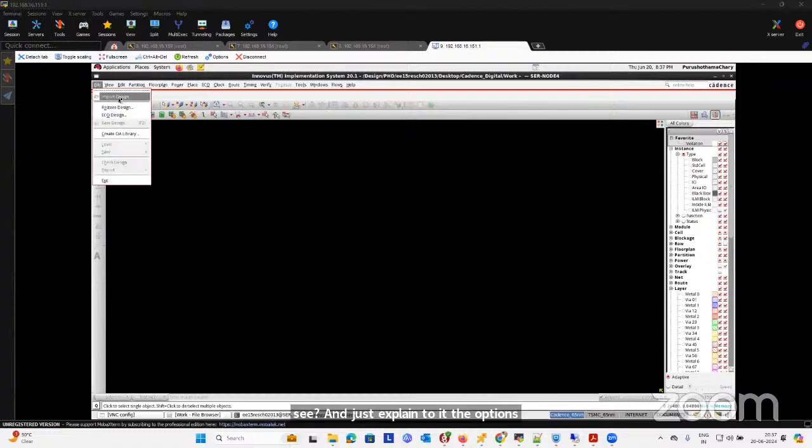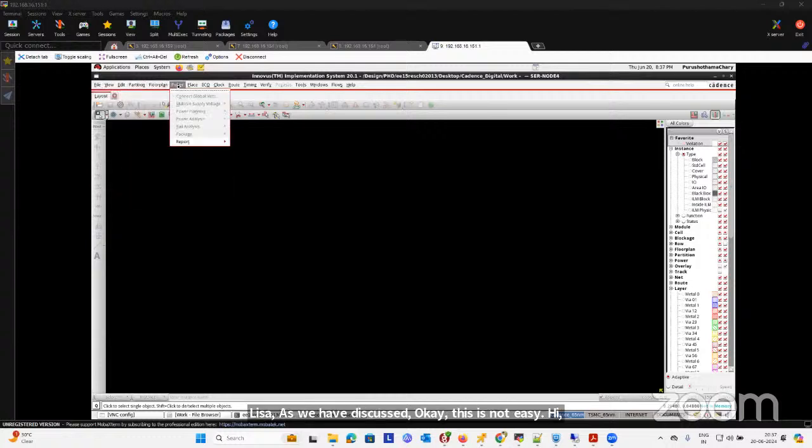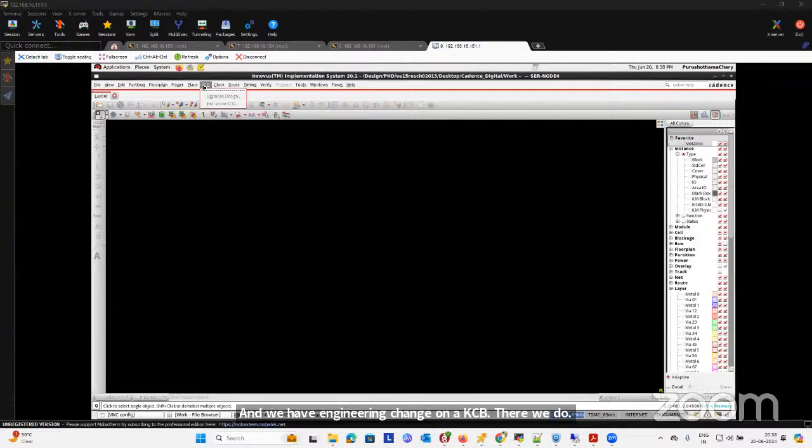These are import design, as we have discussed, and this is about ECO. Next is floor plan, specify floor plan. Next is power plan, which is what we are going to do in the power planning. Next is placement, next is clock tree, next is routing, next is timing analysis. And verify is design rule verification and layout verification. And we have engineering change order, ECO, where we do the timing, power, and area analysis based on our optimization.